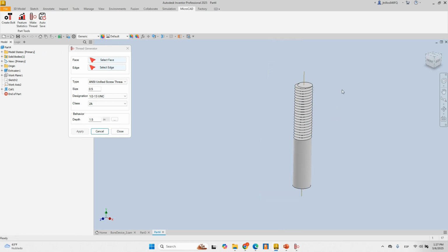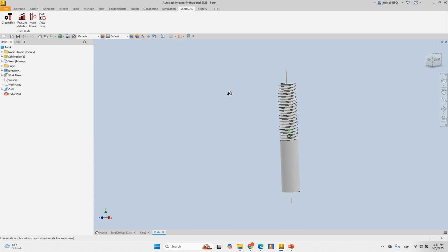Okay, so it's going to be very helpful as well in case you need a head start on creating the coil version. It's going to read the thread, create a sketch with thread parameters based on what you selected right here, and it's going to create the feature as well. Right?